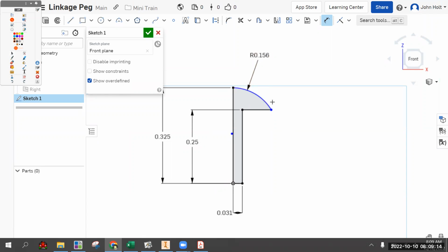If it goes up before it goes down, it will make sort of a dimple on the top. But something that looks like this, let me actually dimension, and I'll just tell you a dimension that will work, which is, let's just make it 0.1. Okay, so let's call the length of this line 0.1, even though before we did the distance from the end point to the center of everything, which this will over dimension it. That's why it's grayed out. But if you just make this line 0.1, you'll be fine.